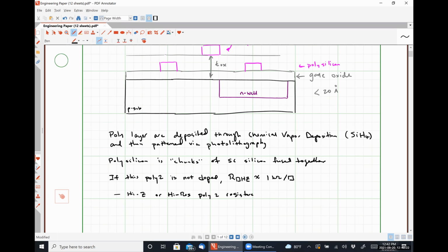So we spent a long time talking about N-well resistors having roughly a sheet resistance of 800 ohms per square in a C5 process. And now we have access to a different way to make resistors, having a sheet resistance of only 1 kiloohm per square in that same process. So the amount of resistance that is increased by using these high res poly layers isn't really that much more, right?